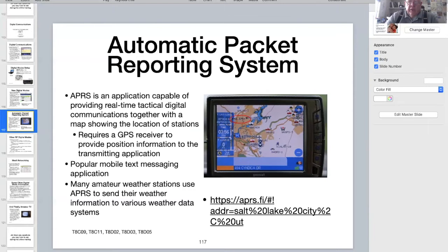I have an APRS unit in my car. It transmits my location when I'm driving. The updates are sent every 2 minutes or whenever I make a turn 25 degrees or more. When we're on our way to visit some of our family, the grandkids can readily see where we are and about when we'll arrive.